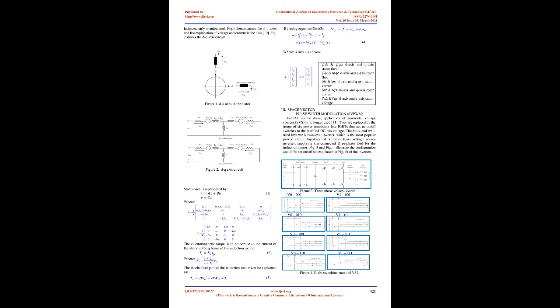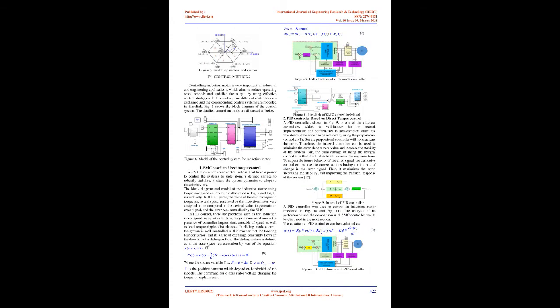Scalar control, or V/F control, is very popular for induction motor drives. It is a quite simple technique to implement. It only requires the value of the magnitude of the supply. In this method the disadvantages are that torque and flux are not directly or indirectly controlled, and the flux variation is slow because of coupling. Control is furnished via a frequency and voltage reference generator to get a constant volt per hertz output. Because of that it gives limited speed accuracy and poor torque response.